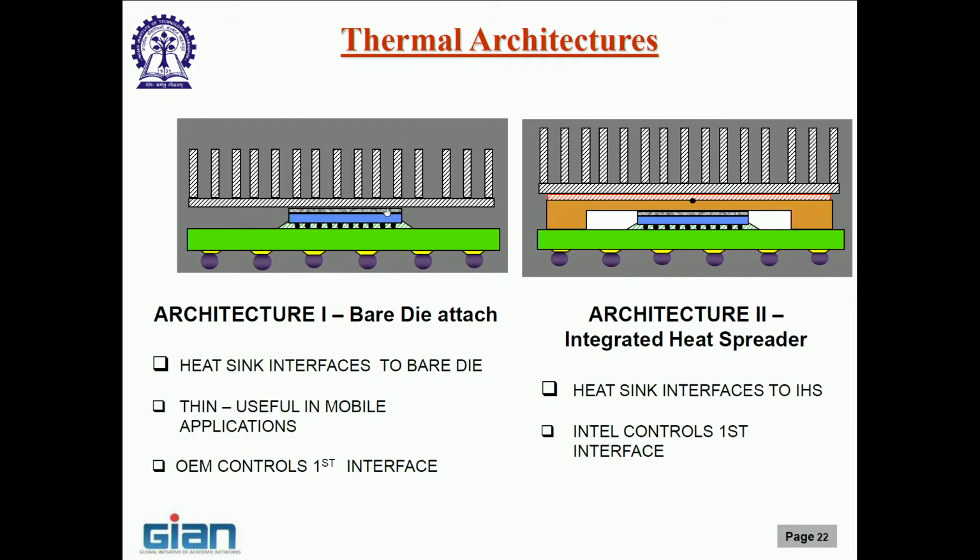It is in a fluid state, but it will not flow out because it is very viscous, but the viscosity is low enough so that it can flow and fill in all the voids. So, next time when you switch it off, the material had already percolated into the pores and filled up the voids. Okay. Next time you switch it on again it melts, but remains in that mushy state, thick enough so that it does not flow out, but still fluid enough so that the voids are all filled in.